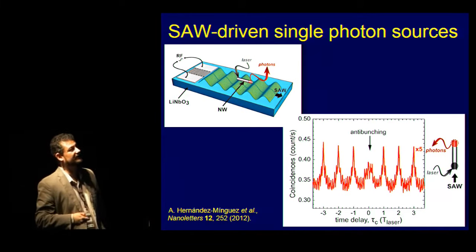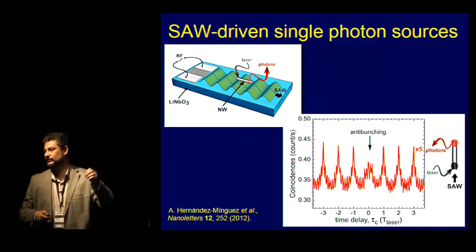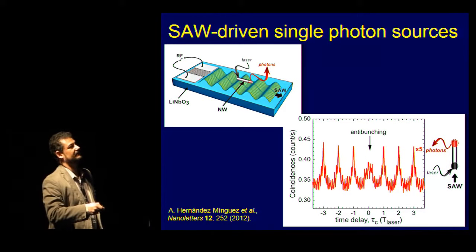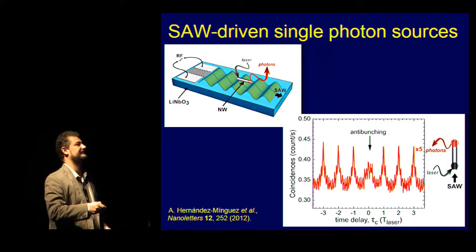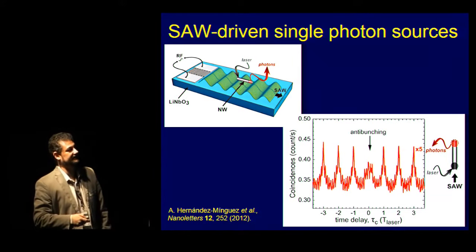So if you do it properly, we can do it in a way that we transport single electrons or single holes, and the first one is trapped there, and it waits. For instance, if we carry the electron first, it comes, is trapped there, and waits for the hole to come next, and then they recombine and emit a photon.